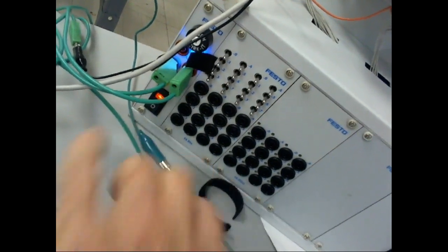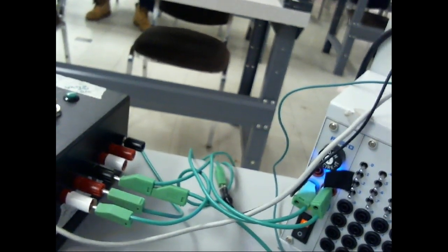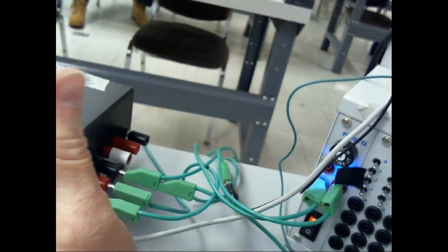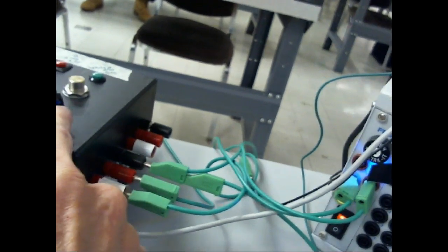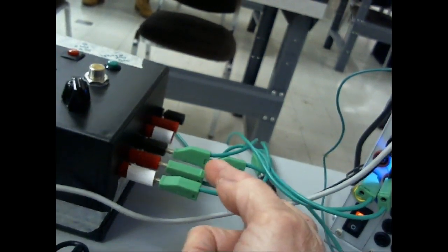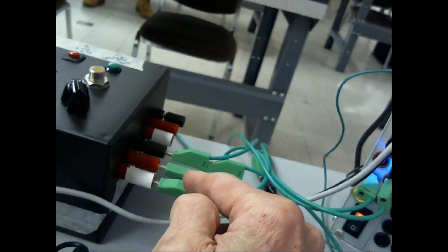So I'm using the power supply off the trainer, and then I'm running it through a circuit that cuts the 24 volts down to 10 volts for the pot. Even though I'm powering it up off 24 volts, I cut it down to 10 volts for the pot using a resistor. It's really amazing. So this goes to my power source, and this is my signal source right here. My power comes in to my pot. This is where I get the power.